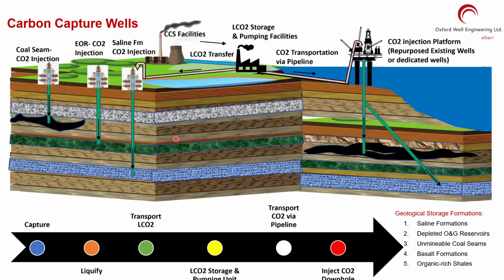For carbon capture wells, you mostly drill vertical wells. If you want to drill a brand new well, you always drill a vertical well, because with vertical, you can connect various layers of carbon disposal places. You can have one here, dispose carbon into this one, dispose carbon into that one. You can have a sliding sleeve, and you can also have repurposing. If you have been drilling previously, you can have a sidetrack going to some other formation and pump the carbon into this one.